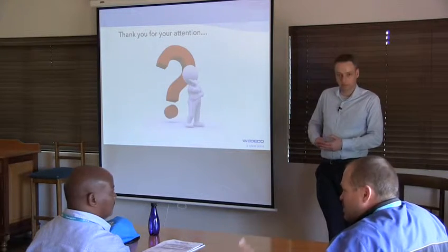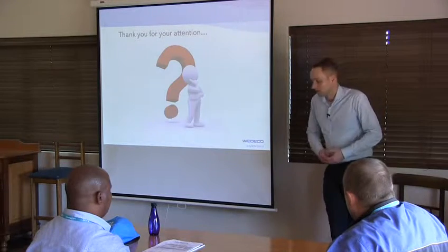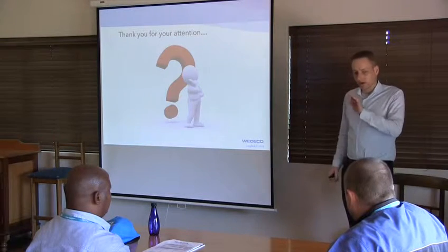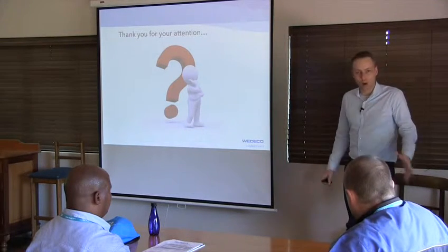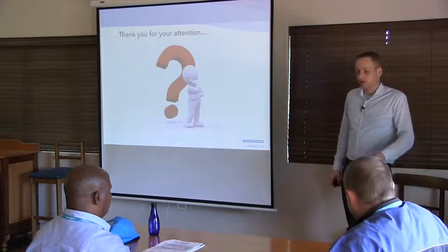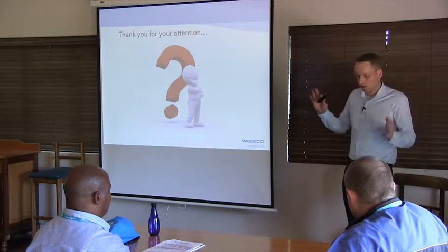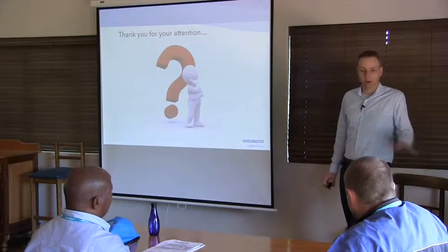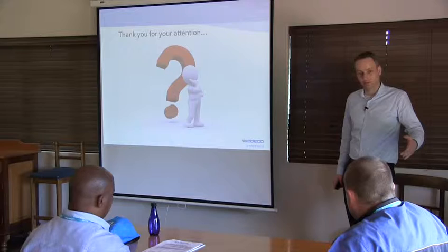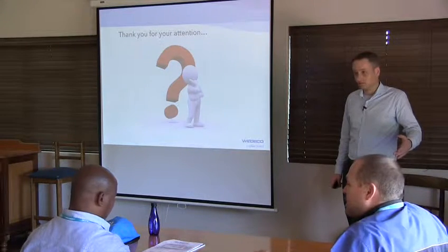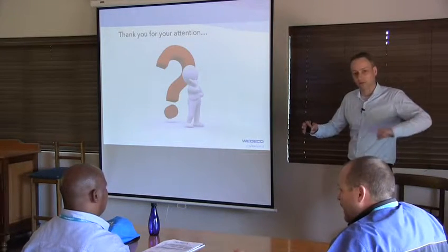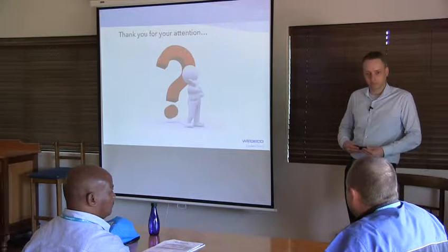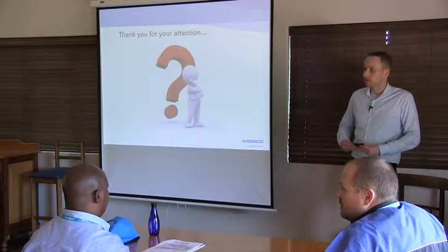And low pressure is up to what pressure? 0.1 bar. The surface temperature of the lamp, not of the quartz sleeve around it, is around 100 degrees Celsius. So for all our low pressure systems, you can have zero flow conditions for over 30 minutes without overheating the system. So it can stand for 30 minutes in standing water with lamps running at 100% power without overheating. Medium pressure is what? 600 to 900 degrees.